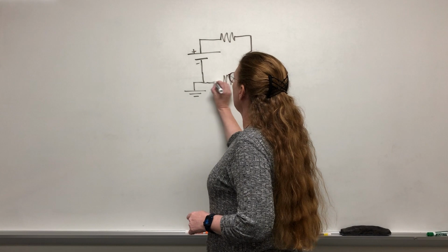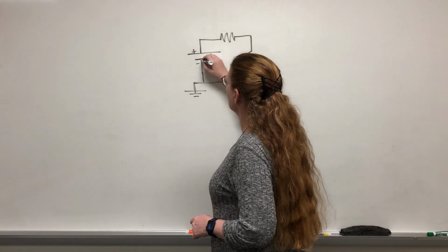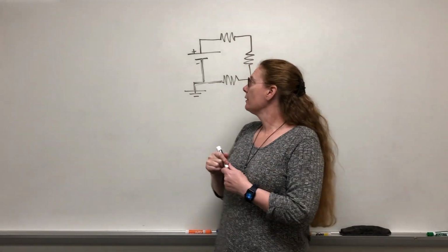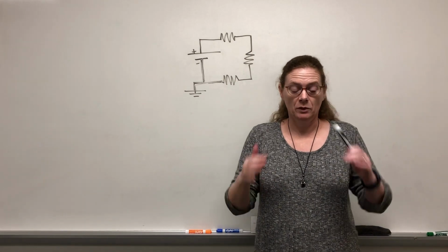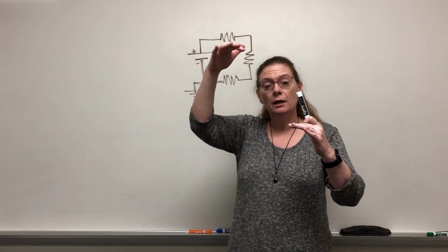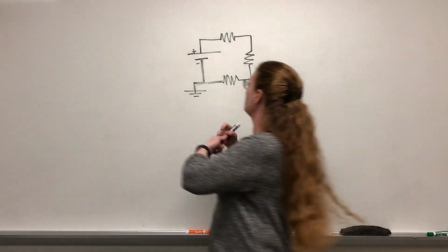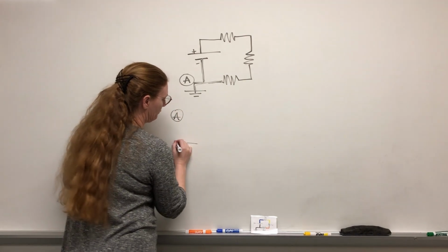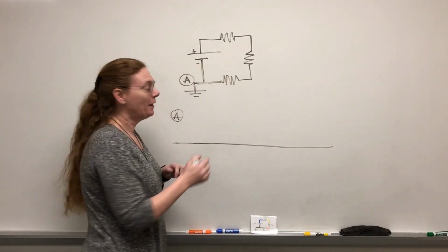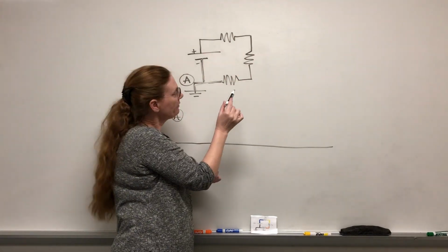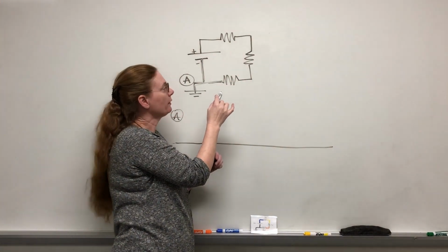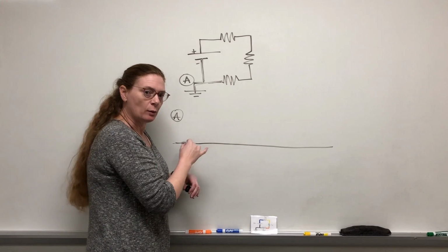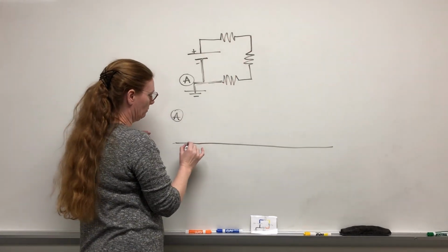So let's say this voltage here is ground level. I'm going to color that black and call it ground level. The analogy I'm going to use is stairs. You can take stairs up to increase your potential. You can take stairs down to decrease your potential. So here, at point A, I'm going to start at ground level, and I'm just going to draw ground all the way through. I'm going to walk around the circuit and figure out what's going on with the potential. Is it going up? Is it going down? And we're always comparing to ground level.